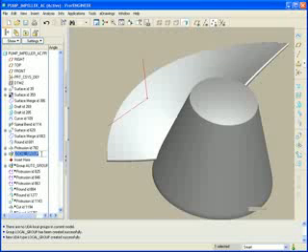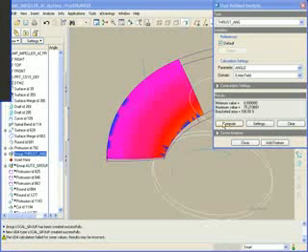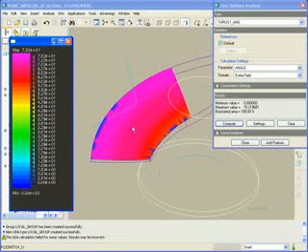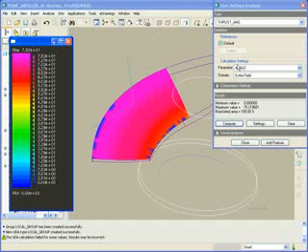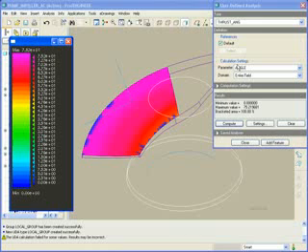So it's just called local group. Let's call it thrust ANG. That'll work for us. When I go to analysis, user-defined analysis, I now have this thrust ANG analysis feature where I can specify and compute over the entire, let me put this into the screen too, over the entire domain. So the field point exists in a domain, and what Pro/ENGINEER's done now is it's moved that field point around on that surface, creating now a plot.